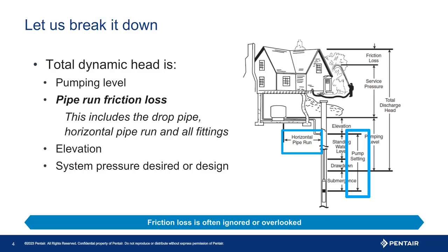Now if you are intimidated by math, do not worry, the heavy work has been done and charts created to streamline the process. What pipes do we have to calculate the loss in? Well, first, where is the job done for a pump professional? The answer, easy, the pressure tank. So, any pipe from the tank to the wellhead and down to the pump set. Even if a portion is underwater, we still calculate down to the pump set, as the water is moving faster than nature intended through the entirety of the piping. So, let's look at the charts.